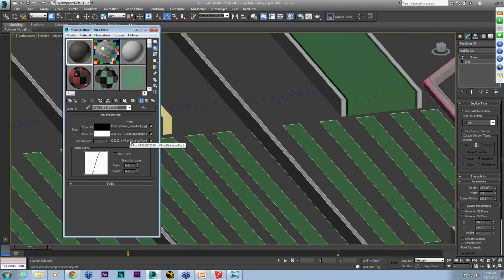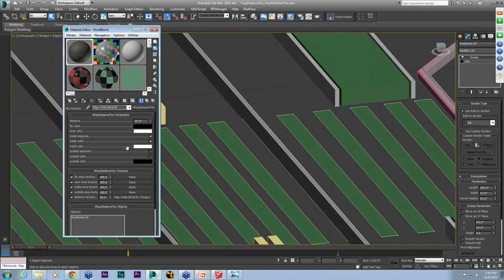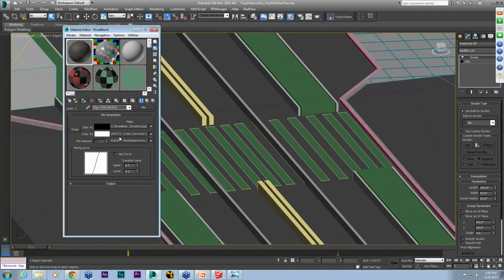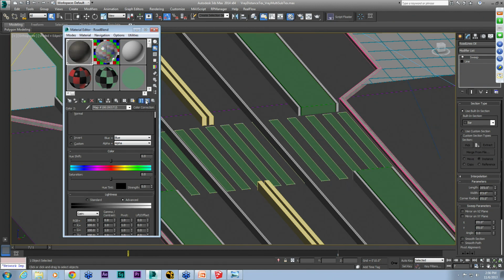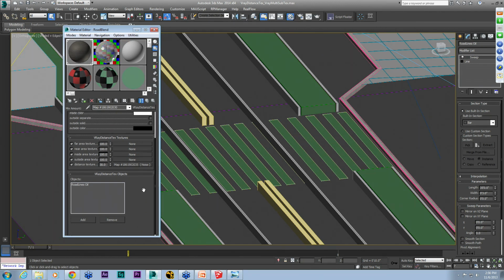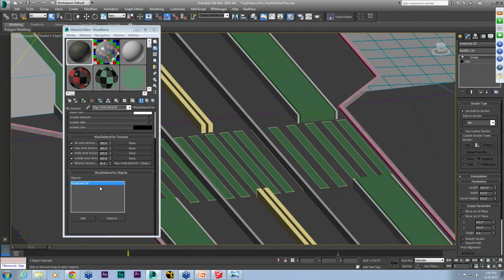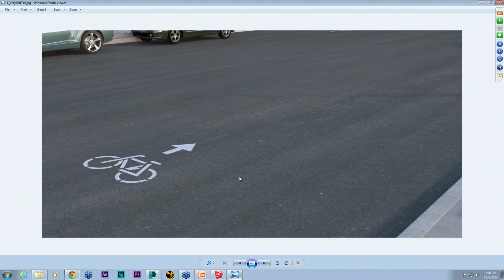And then we have the V-Ray distance texture, which is just saying like 2.5 feet from this object, plus the inside, which will be solid, make this darker. So here's the darker. It's 0.8 gamma over that section. And it just kind of fades out, and I usually use a noise in the distance texture radius, just to give it a little noise, because oil isn't so linear. And you just tell it what to affect. So we've got the road lines oil right there.